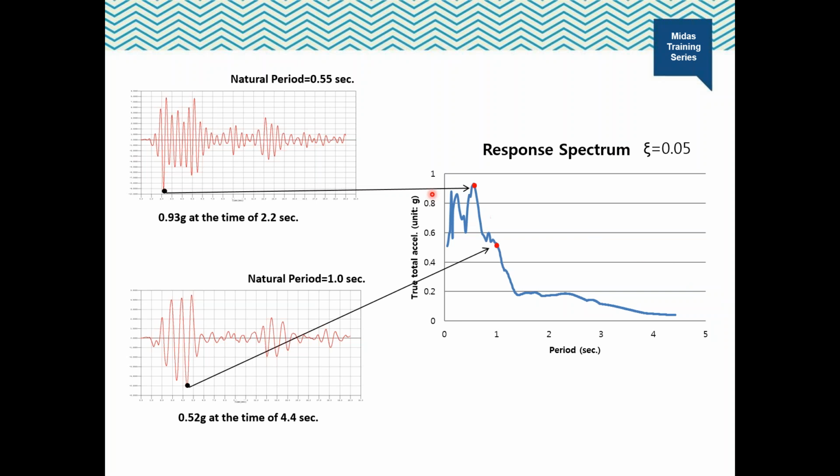The peak total acceleration for the SDOF system with the natural period of 0.55 seconds is 0.93 g, and it occurs at 2.2 seconds.